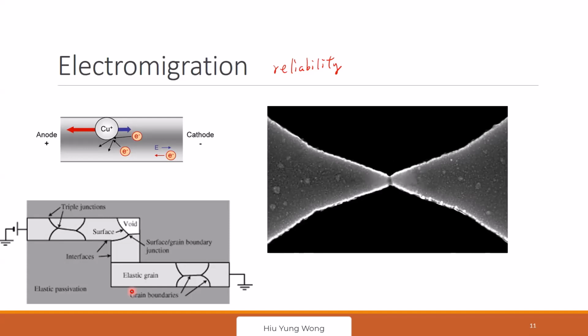So for example, sometimes you are not allowed to put the metal on top of something. You would rather let the current signal go from here to top instead of top to bottom, because this is going to have different electromigration and different reliability. So all you need to know is to just pay attention to this. We are not teaching this, and actually I don't know well how to do design with reliability, but this is very important. Okay, any questions?